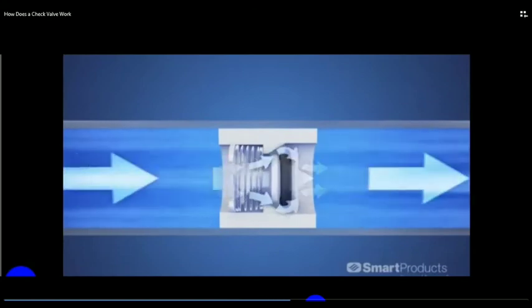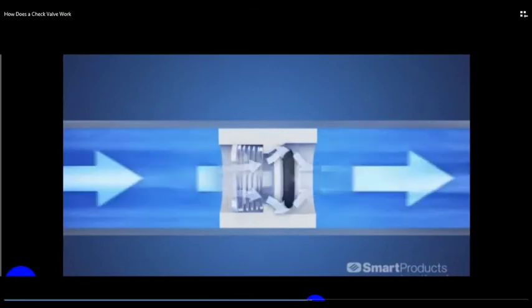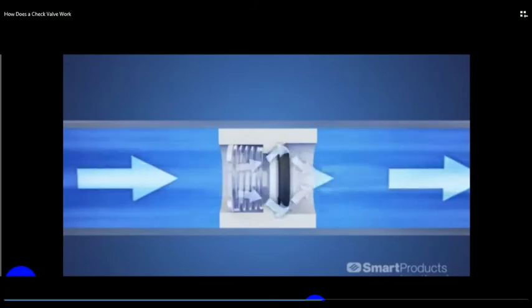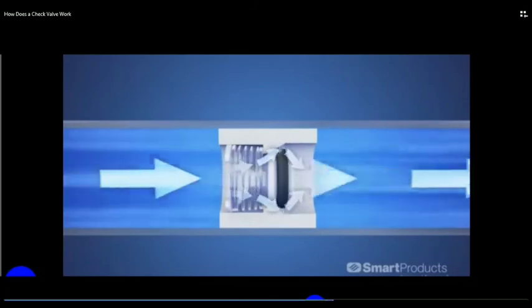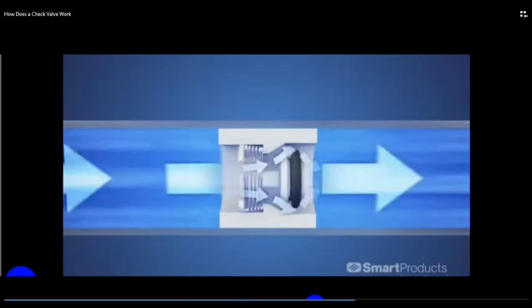Once pressure builds, the O-ring lifts off and there's significant flow. We are now able to assign the opening pressure, one that exactly suits your application design criteria. With the valve fully open, the poppet travels to its limit. To raise flow beyond this takes a large increase in pressure. It's always good to order a valve with sufficient flow for your operating pressures.